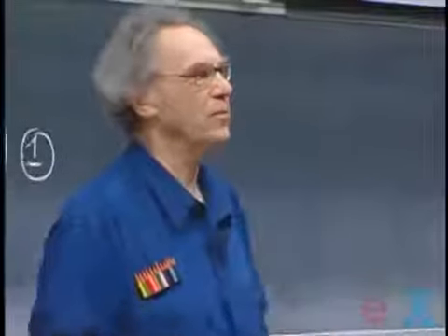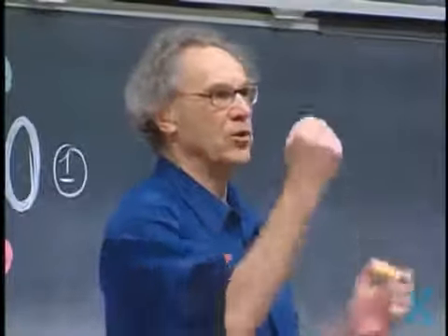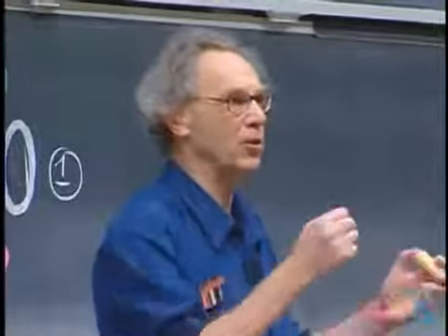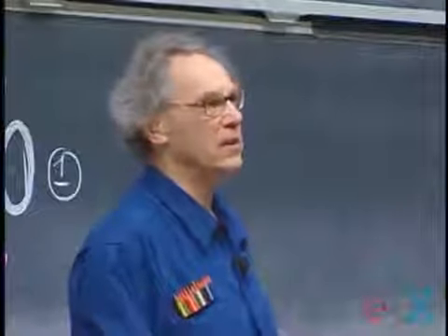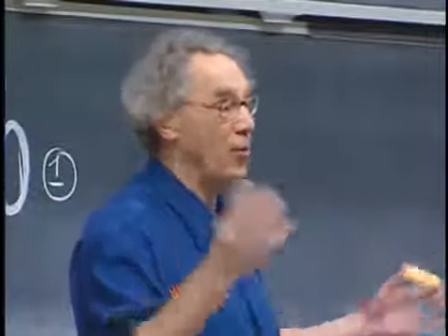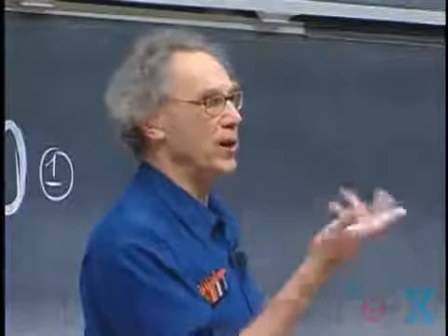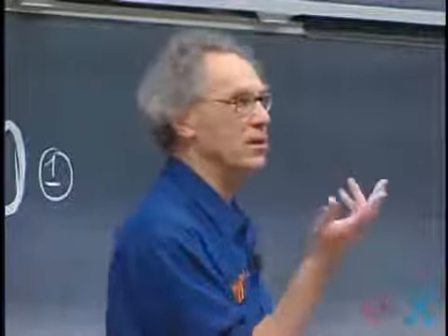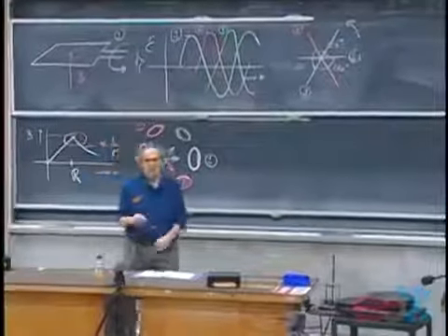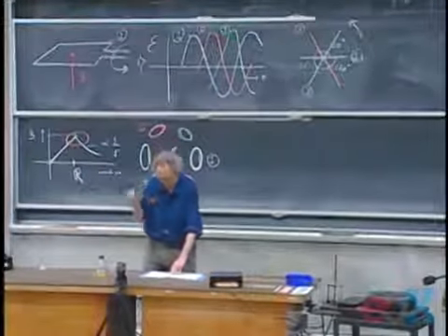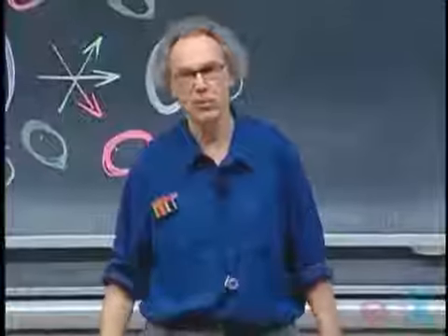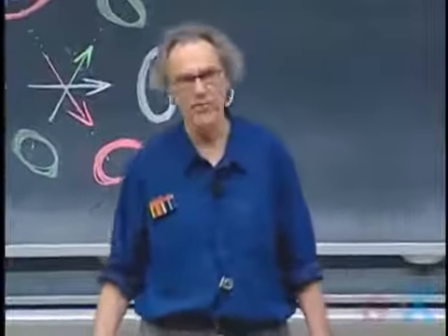In a similar way, when we discussed earlier the idea of a motor that you were going to build, there was a magnetic field and there was a current, and that caused a torque. In the same way, you get a torque on the eddy current. And so it starts to torque up this conducting sphere. And all the time there will be eddy currents because the magnetic field keeps going around. And so you're going to get a torque which will always be in the same direction, and this conducting object will now start to rotate, and we call that an induction motor. Induction motors have no brushes.